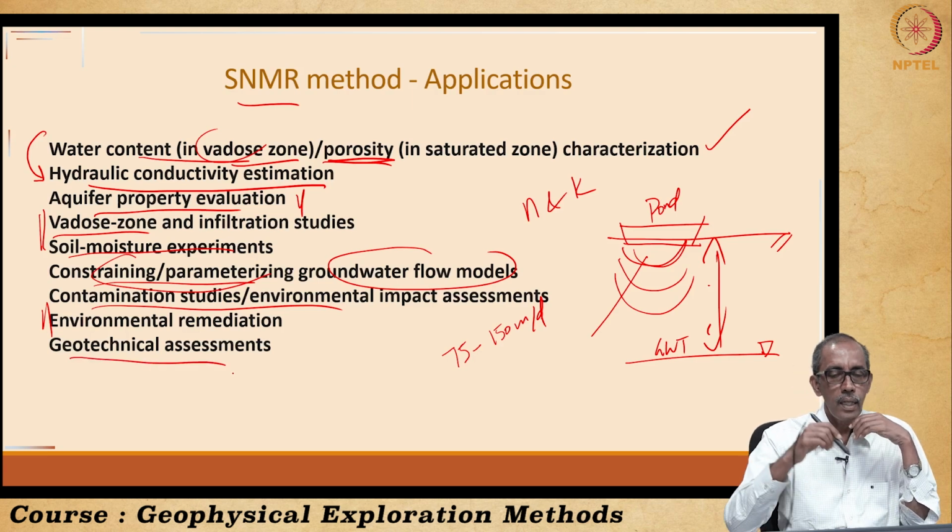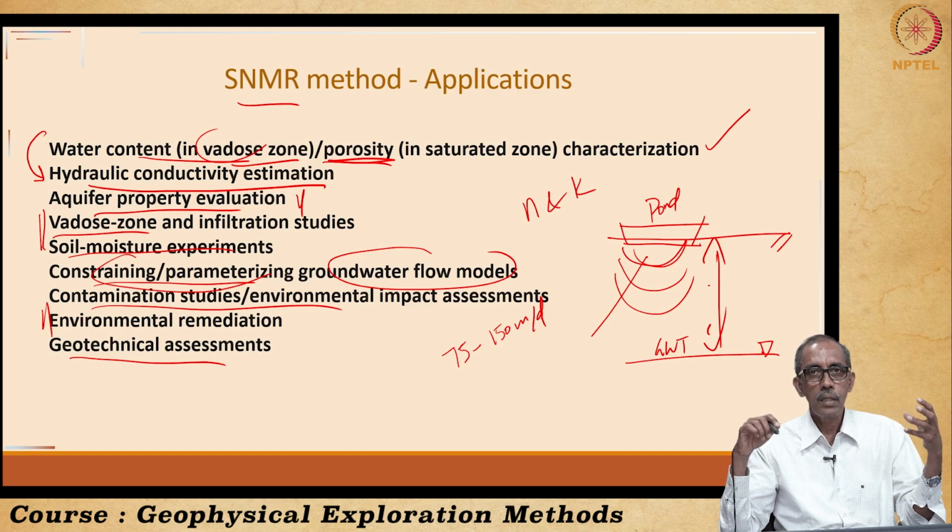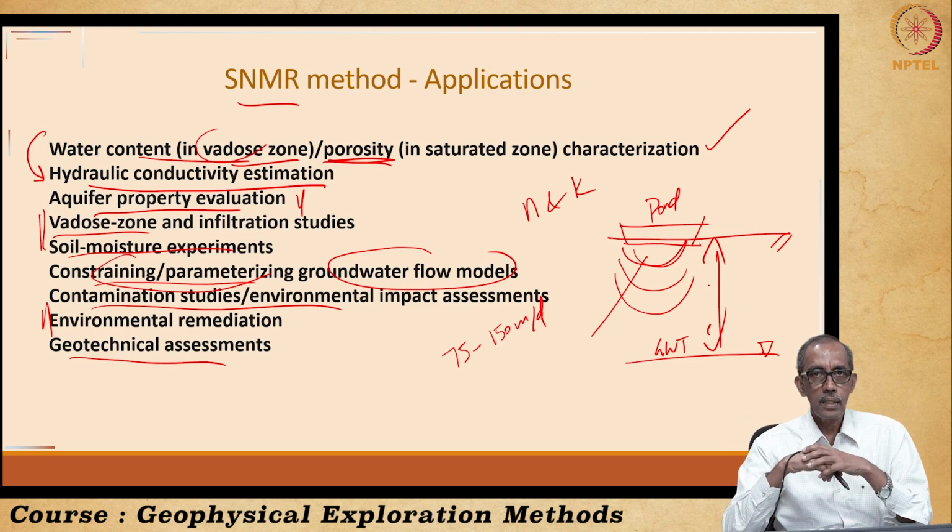In geotechnical assessments, porosity very much helps us. Formations with very high porosity are likely to be very fine grained. So, the presence of clays, which are a hindrance for major constructions, can be deciphered very nicely using SNMR techniques. These are all the broad applications of SNMR.